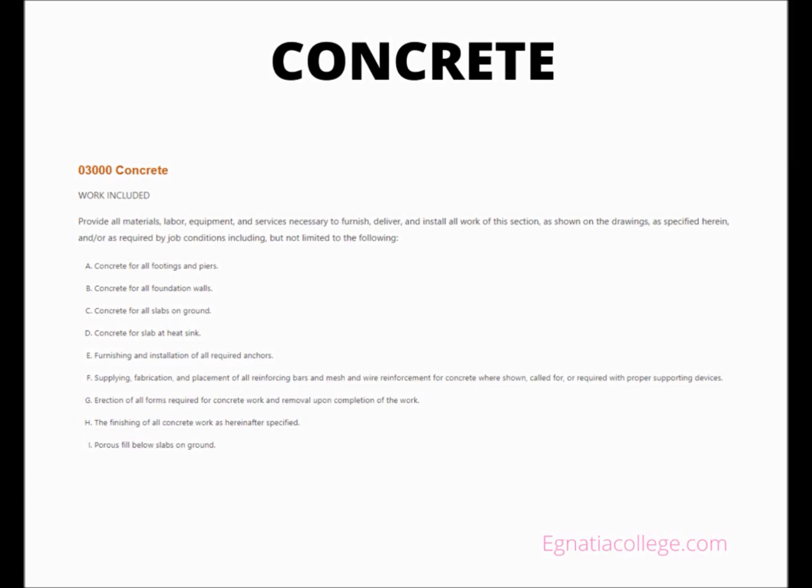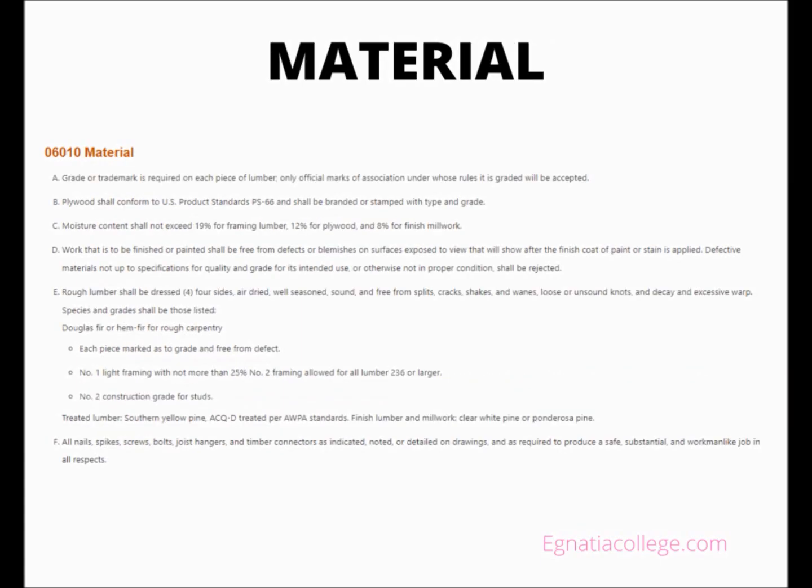Material. Fine aggregate. Fine aggregates for concrete shall consist of natural sand having clean, hard, sharp, uncoated grains free from injurious amounts of dust, lumps, soft or flaky particles, shale, alkali, organic matter, loam or other deleterious substances. Coarse aggregate, stone. Coarse aggregates shall consist of crushed stone or gravel having clean, hard, strong, durable, uncoated particles, free from injurious amounts of soft, friable, thin, elongated or laminated pieces, alkali, organic, or other deleterious matter.